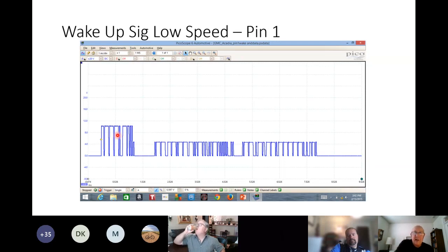The modules have to be asleep, otherwise the battery's going to be dead the next morning when a person comes out. So we know the modules are supposed to go to sleep when we turn the key out and we lock the door and walk away from it in a matter of 15, 20 seconds, or as much as 5 minutes. Otherwise the system will stay alive and be drawing current, okay? So when we want to wake the system up after it's been asleep, how do we do it? Well, we have to have that 60 ohms, and then the second thing we have to have is a signal which comes from the gateway. And this is the only time when I emphasize the gateway. How do we get this whole thing started?